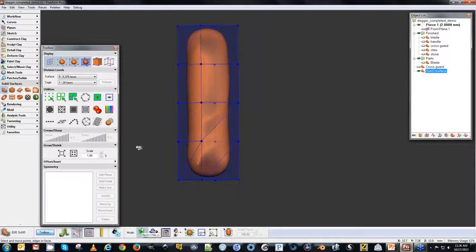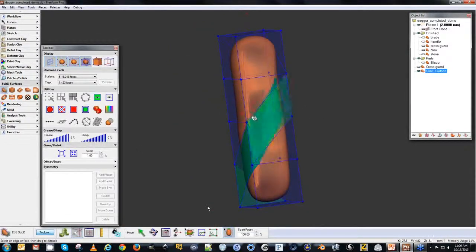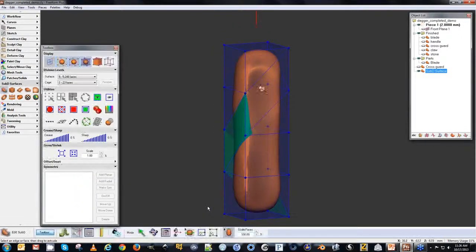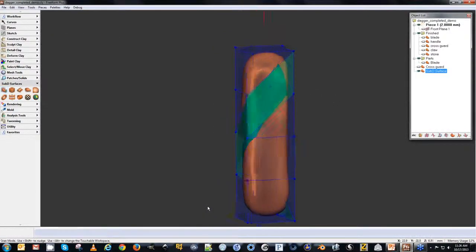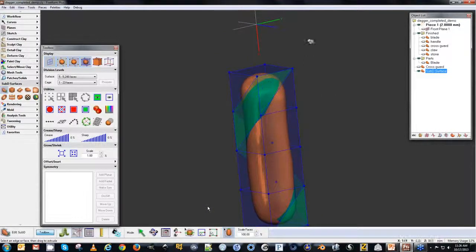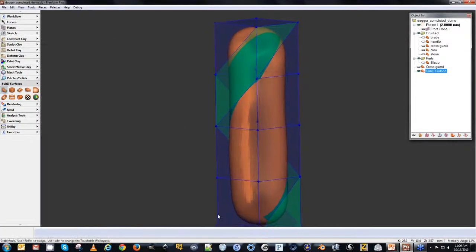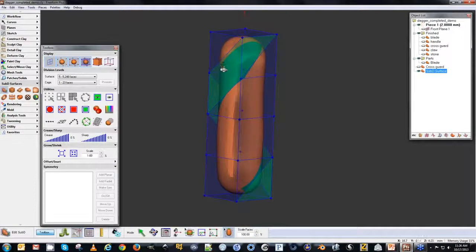So now that I have that part done, I'm going to show you what it's going to look like to create one strip. So entering my extrude tool, I will select the faces that I just prepared. Go around. And now what I'm going to do is I'm just going to extrude these out from the surface, creating new geometry.